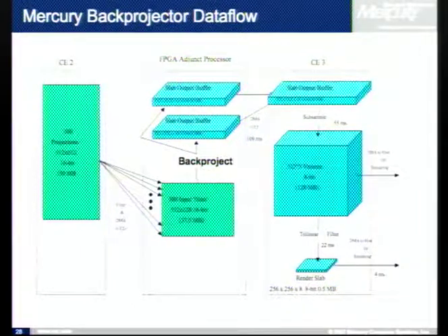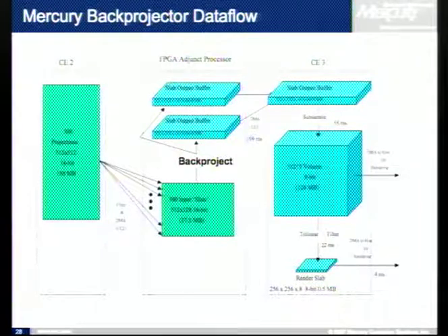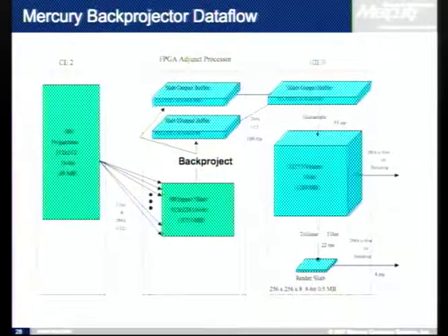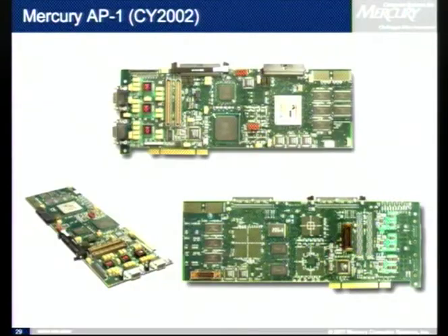Interesting about this, again, why did this work so well with FPGAs? It was a precision significantly less than what you would use single precision float for. So while previous solutions might have done all of the single precision floating point, it was found that we could get within an LSB or two by using the 18-bit multipliers that in that time frame had just started to appear inside contemporary FPGA architectures. So this board, the extended length PCI board, was one of the first FPGA boards that Mercury had done. Before then, Mercury had